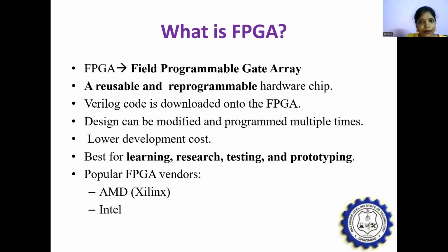FPGA stands for Field Programmable Gate Array. So what does FPGA mean? It is generally a hardware chip, and this chip is reusable and reprogrammable. Once code is written using Verilog, we convert that Verilog code into a bitstream, and then this bitstream is downloaded and uploaded into the FPGA board.